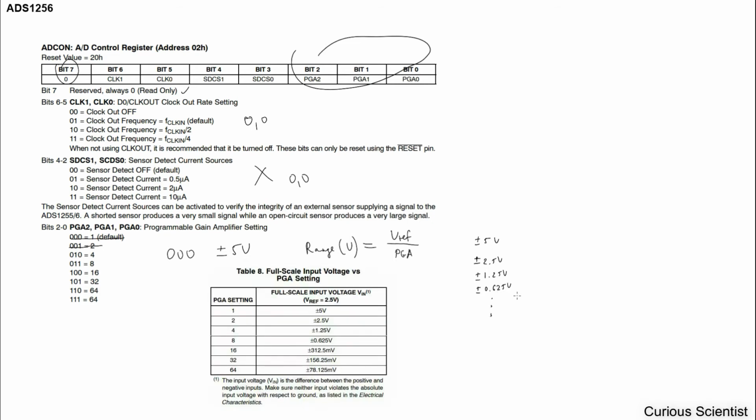So you can go down to quite small voltages, and here you will start to see the importance of this. If you have a voltage which is close to 5 volt and you want to measure that, you use the 24 bits and have the minus 5 volt to plus 5 volt scale divided into 2 to the 24 equal parts.